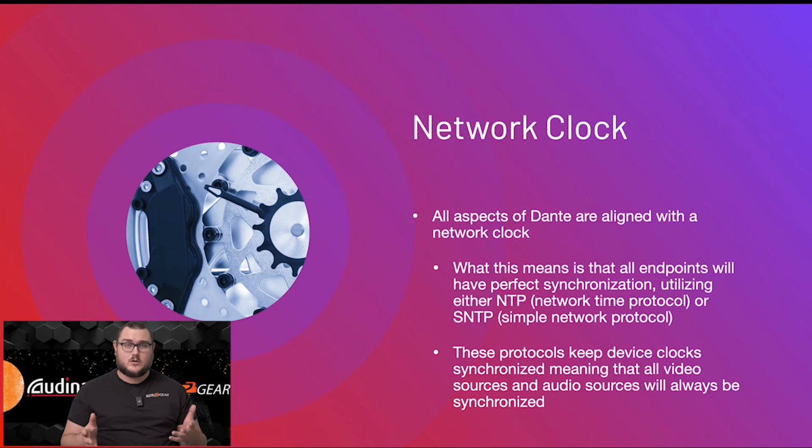Moving on though, you also are going to be getting the network clock. Why the network clock is an advantage is it means that all aspects of Dante, whether that's video or audio, are going to be aligned. That's part of the reason why Dante has hardware involved in its products and why it's a little bit more of a rigorous testing process. So all of your endpoints should have basically perfect synchronization utilizing either network time protocol or simple network time protocol, or SNTP. So really awesome that is included with Dante AV-H.